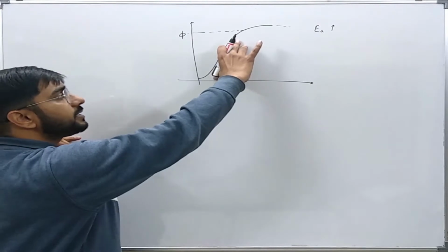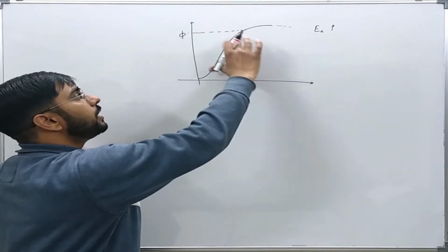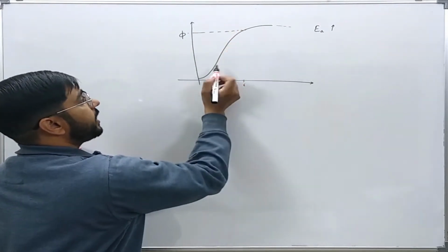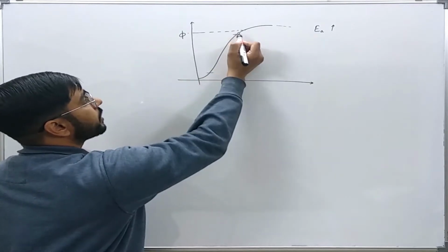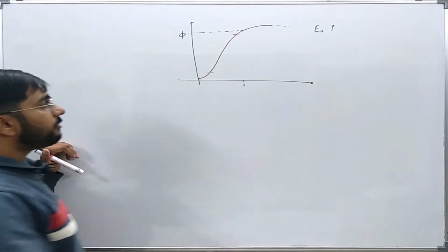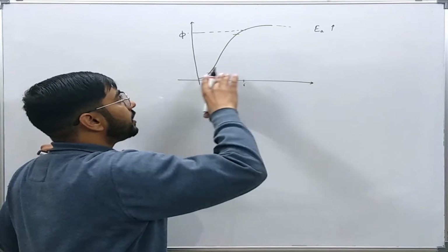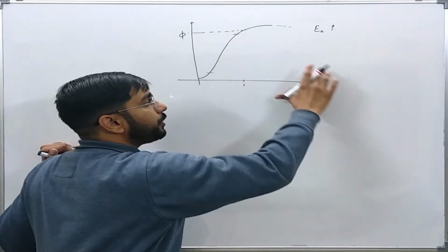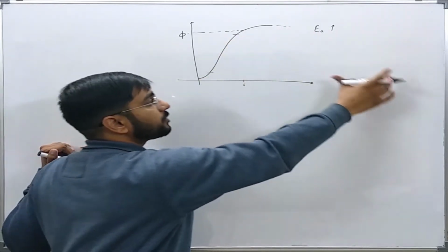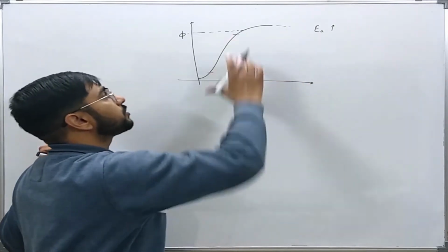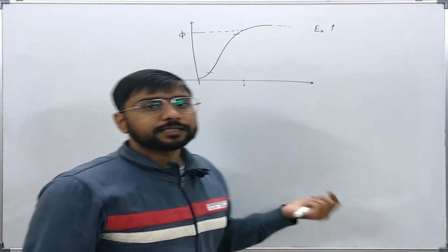Initially, when the CT is working in its linear state, it will faithfully try to reproduce the primary current in terms of the secondary current according to the turns ratio.